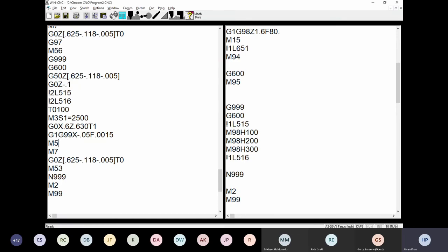It's just like a start position in the subprogram for the last part programming. So you don't have to cancel that G50. When you use the G50 with incremental, then you need to cancel it. In this case, no, you don't have to. This G50 right here, I think it's the one that you're talking about, right? All right, is there any other questions?